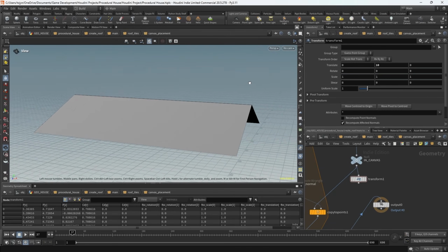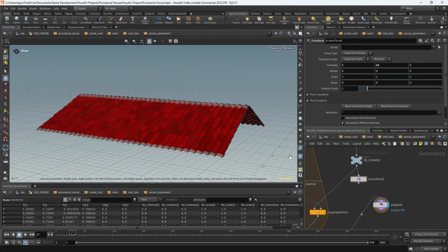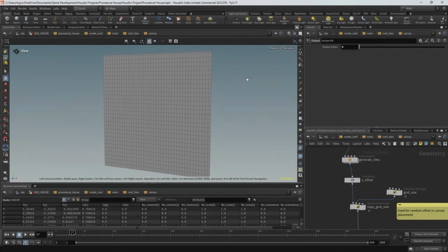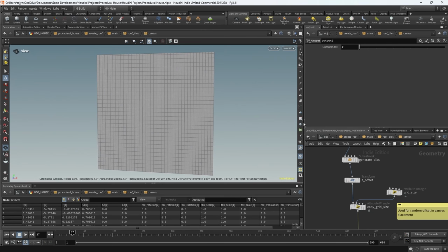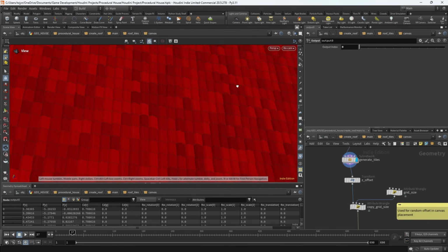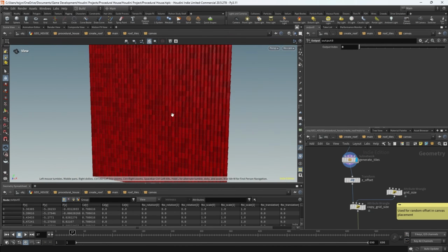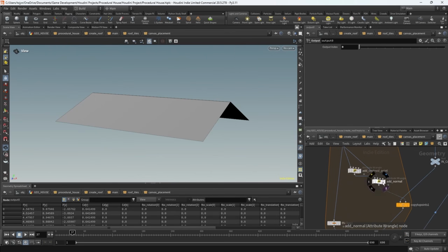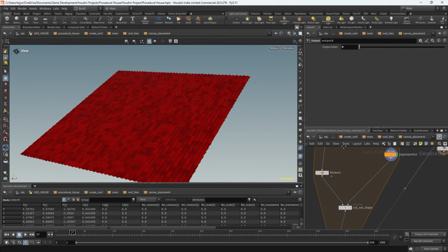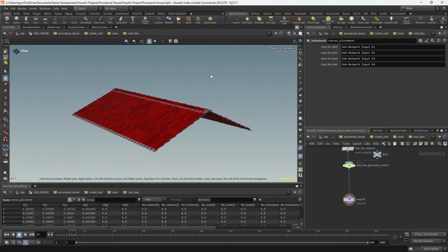The logic for spawning default tiles is quite complex, but in a nutshell, there are two steps: creating a tile canvas and placing the canvas on the flat parts of the roof. A tile canvas is basically a huge grid of tiles with random orientation and vertex colors. The area of the canvas should always be bigger than the area of a roof side. Gladly, the code handles that. After I get a tile canvas, I orient it along the roof side and cut the parts that go beyond the roof. And that's how roof tiles are made.